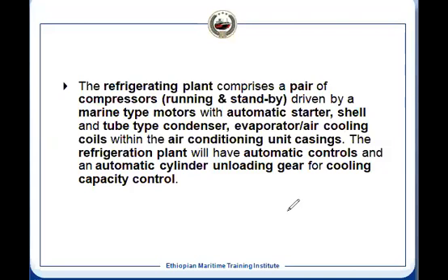And the type of condenser we use is the shell and tube type condenser. It means the heat exchanger, we have seen the shell and tube type heat exchanger. It is exactly the same type of heat exchanger. And here, as in the refrigeration system, the shell fluid is the refrigerant, which is at high pressure, and the tube fluid is water which is passing.